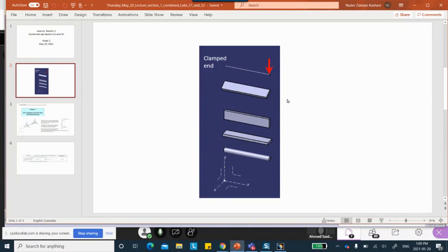In planar beam problems it is fine, but if a beam is oriented in space, then you also need to give it some information beyond the shape and the dimension. Give it information which tells you, is it oriented like that, or like that, or like that? Because each one of them will behave differently. The only case where you don't have to specify orientation is when the cross section is circular. Notice that if you turn the circle around 90 degrees, 35 degrees, it doesn't matter. It doesn't affect the response of the beam, because a circle is a circle. It doesn't matter how much you rotate it. But for the other cross sections, the behavior of the beam is different, oriented like so, or this one, or that one.